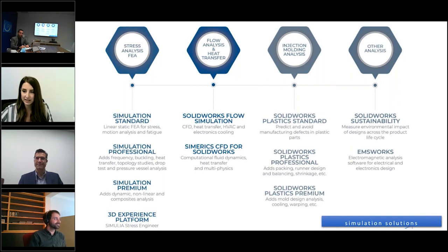Awesome. Thank you, Jonathan. Roman, I think this one might be best for you. So the question here is, what is the selection criteria on when to use SolidWorks Structural Simulation or SimuliaWorks? Yeah, so the real key difference is 2 things, actually. If you are required to do simply a linear analysis, then you can pretty much stay with SolidWorks Simulation.